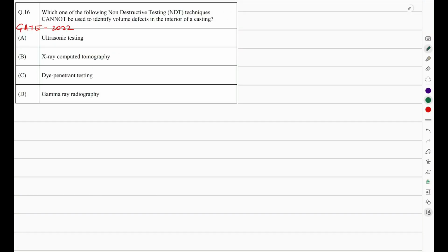In this video we are going to see question number 16 of GATE 2022 question paper. According to the question, which one of the following non-destructive techniques cannot be used to identify volume defect in the interior of the casting? We have four options here: ultrasonic testing, X-ray computed tomography, dye-penetrant test, gamma ray radiography.